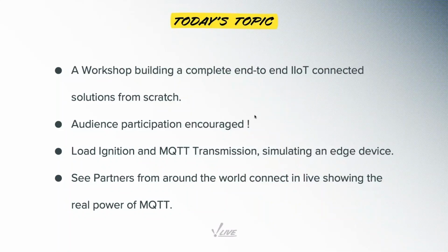So today's topic is a workshop to build a complete end-to-end IIoT connected solution from scratch. We're going to load Ignition and the MQTT transmission module, simulating an edge device from your home office, your basement, wherever you're coming in from, and then see some of our partners around the world connecting in as well, showing the real power of MQTT.